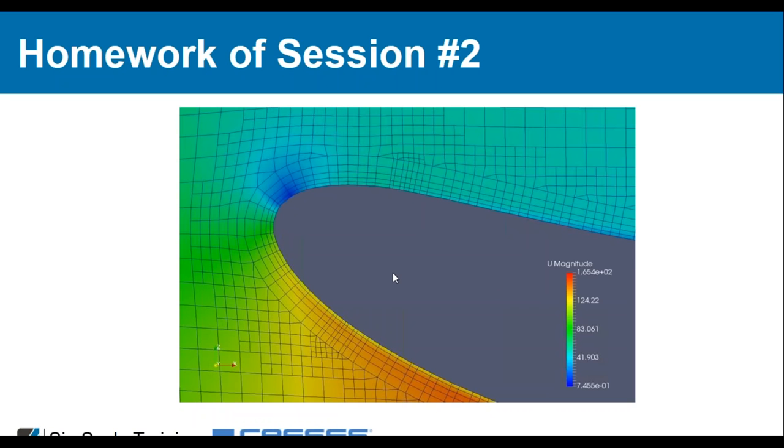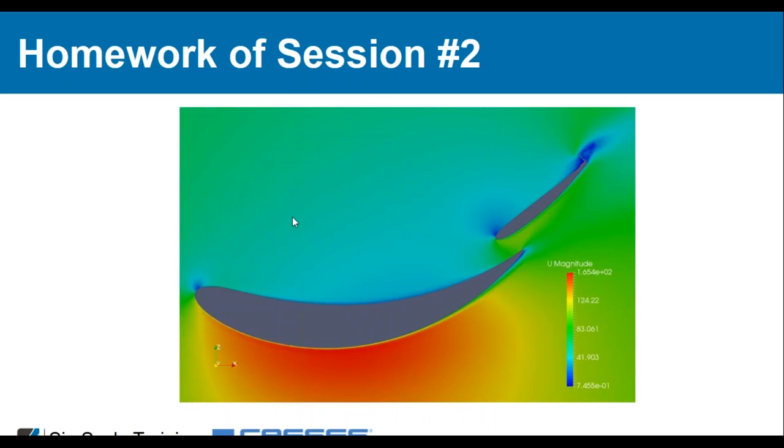Okay. Then, for example, here you can see the velocity distribution on this main plane and the edge of the cells. And here we have the stagnation point, by the way, where we have a pressure coefficient of 1, the highest static pressure. Then let's also take a look at the velocity distribution for the whole wing. Here you can see a separation here and a separation here. And to resolve the separation, by the way, the layers are essential.